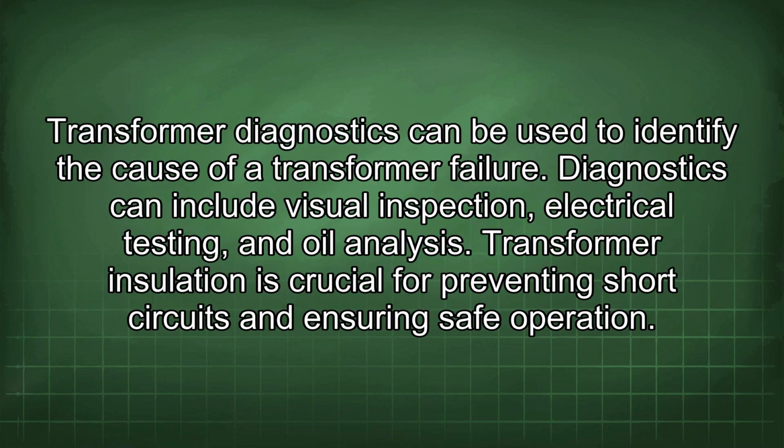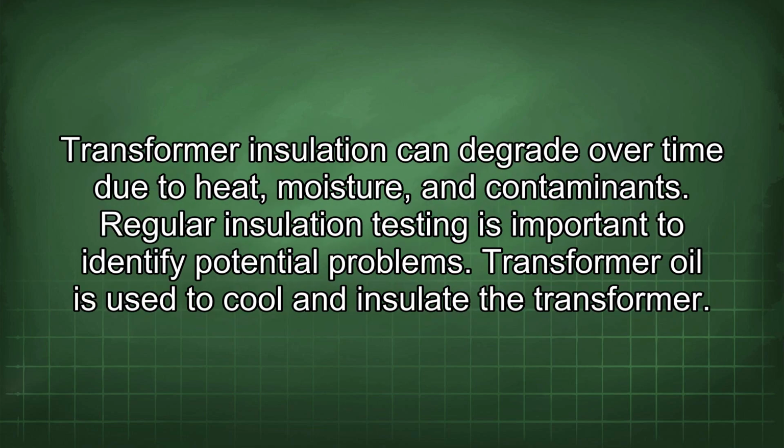Transformer diagnostics can be used to identify the cause of a transformer failure. Diagnostics can include visual inspection, electrical testing, and oil analysis. Transformer insulation is crucial for preventing short circuits and ensuring safe operation. Transformer insulation can degrade over time due to heat, moisture, and contaminants. Regular insulation testing is important to identify potential problems.